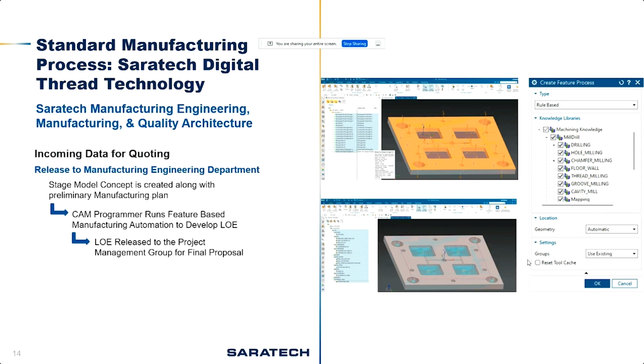Our manufacturing engineering department would run through sophisticated templating of stage modeling, to where they would interrogate the model and build the best fit stage model for that particular part within a set of restrictions and requirements that we built into the system. Then it runs through a system of feature-based manufacturing where it interrogates the model and then looks to those libraries, and it automatically programs the part to that point. Then it goes to a peer review, to where it will go to a programmer. They will sit down and say, okay, go through the level of effort, add to, or sign off on that level of effort. Once it goes to the customer and they approve, it comes back to us.